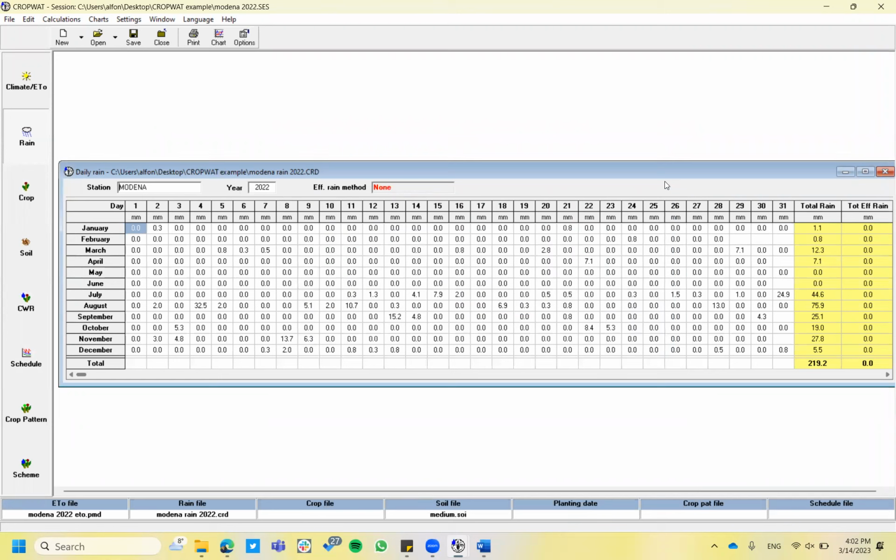Okay, so what have we learned from Cropwat so far? It helps us manipulate the different systems, allows us to quickly obtain the total amount of water needed based on the efficiency of our system, and allows us to tailor the estimation of crop water needs with local information like soil type, weather data, and also the crop coefficients.